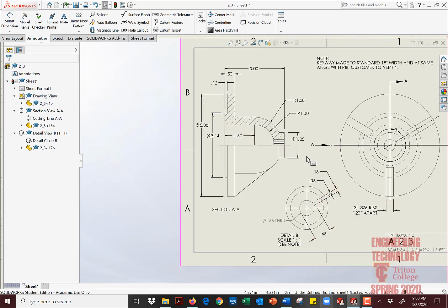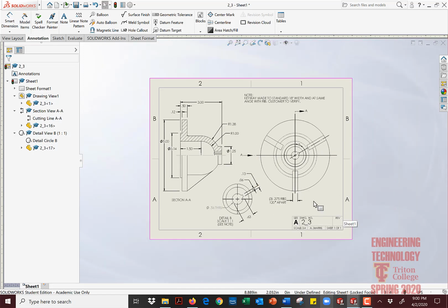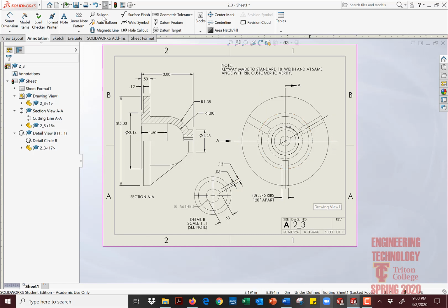So that's okay. Now when we look at this drawing, the question is, are the line weights what you want them to be? Okay, before you do anything, hit save. Save, save, and save often. Are the line weights where you want them to be? If they're not, now is the time to fix it. The best way to find out if the line weights look good, visually it might look okay. Personally, it doesn't look okay to me right now because it looks like my dimensions pop, but my object does not. It actually should be the opposite. Your object should pop and your dimensions should be subdued. They should be a little bit less poppy. They shouldn't be so bold looking on the piece of paper.